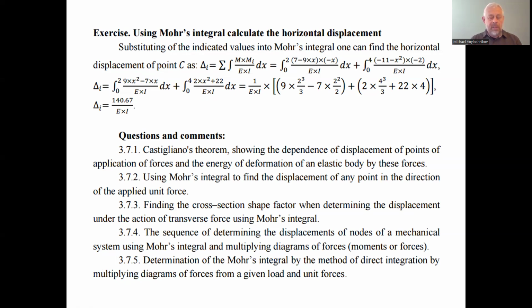This theorem is the ground of the Mohr integral, for finding the displacement of elastically proportional mechanical systems for the flat state, as we considered in the example, or the spatial state. Spatial we can consider for six displacements due to the 6 axes in space.